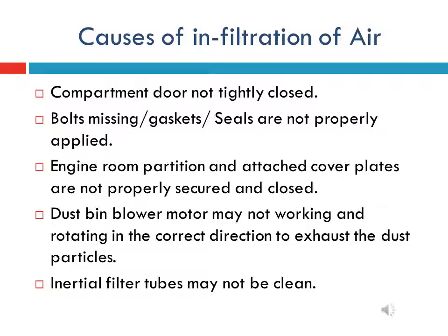First, as mentioned in the slide, if the compartment door is not properly closed, in that case also unfiltered air may enter the air compartment. Second, there are so many bolts and gaskets provided at the lower end of the cyclonic filter. If some bolts are missing or a gasket is damaged, in that case also the air may enter the air compartment.